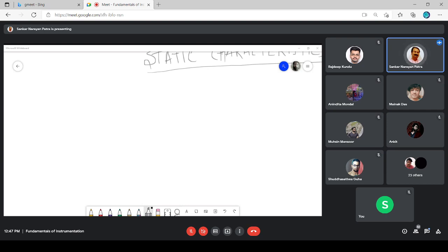Then I have to go for some kind of static calibration or measure what the other influencing parameters are. Influencing parameters other than the desired signal should be ignored or held constant, so that they cannot influence the instrument much. If we can do this for the span of measurement, then we can say it's a calibration.